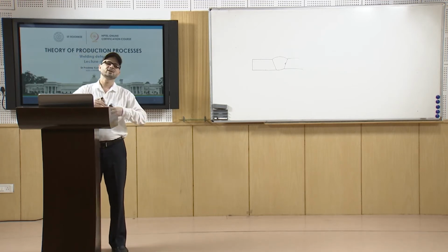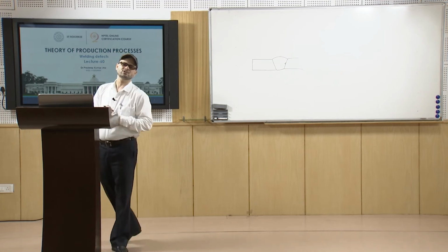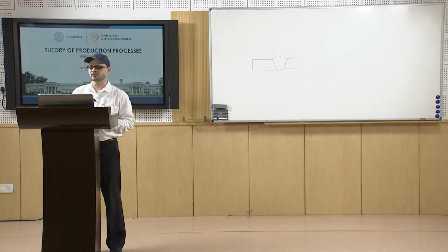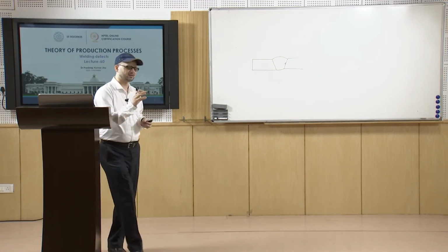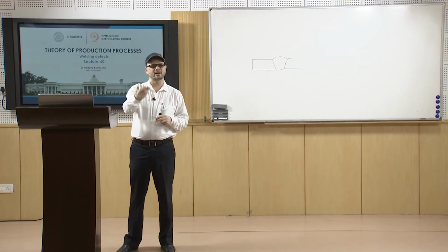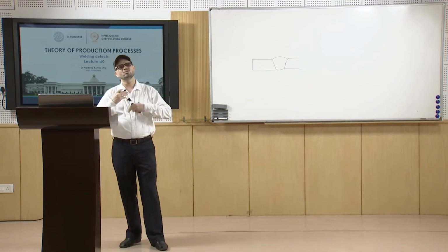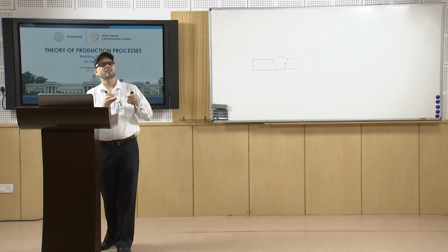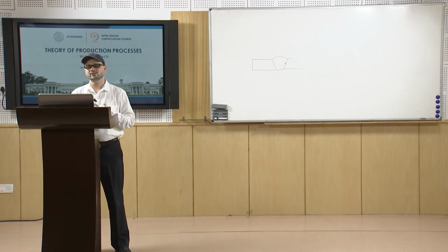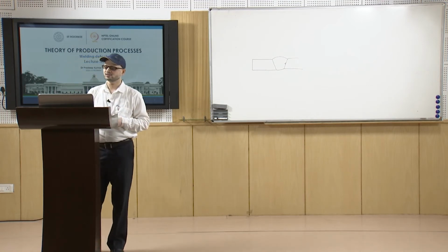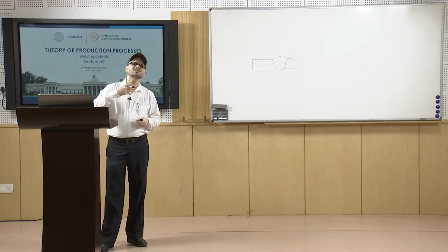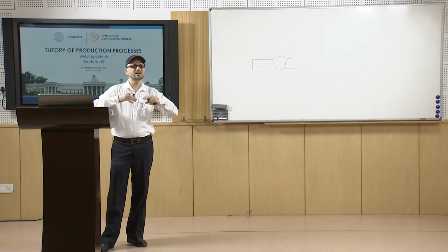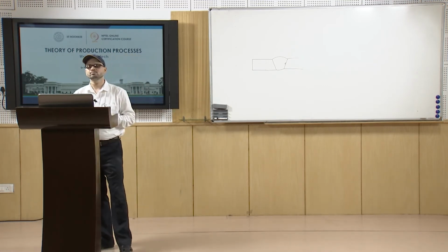Similarly, you have the incorrect application of the welding process itself. You are not doing the process correctly, like putting the improper current. The current has to be higher for more deposition, but you are not putting in adequate current. So, the defects may come because of this improper welding process. Many a time we have inadequate metal deposition, and we may have excess metal deposition also.